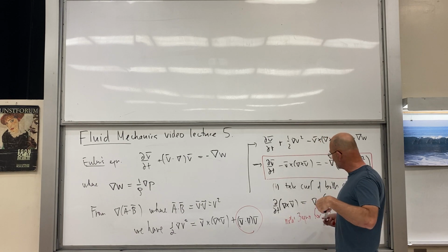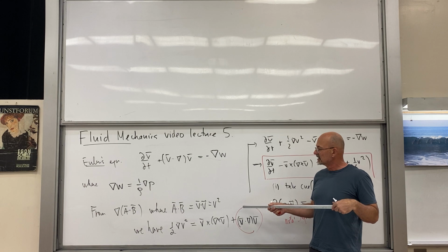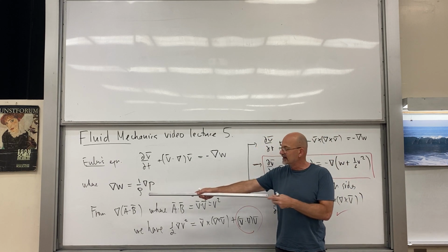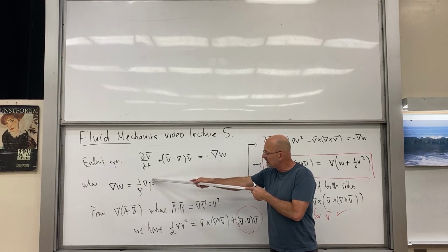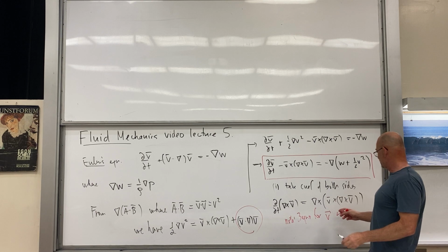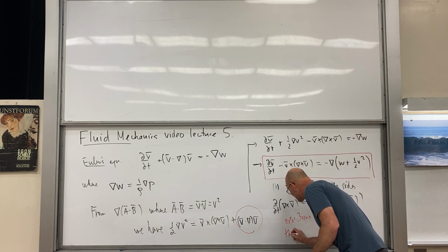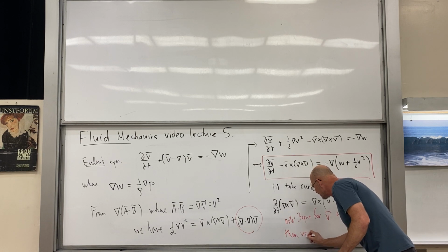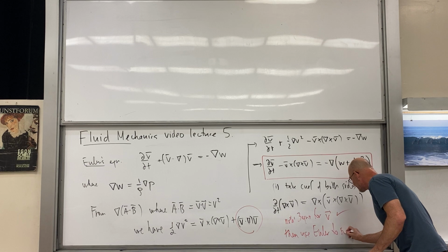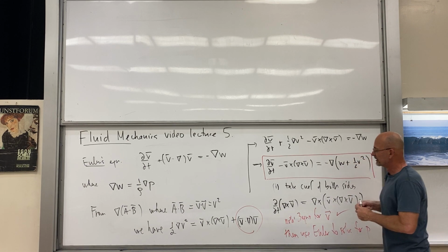Or you can go back into the original Euler's equation and solve for p. Because the density, which you'd also need, is actually just a function of position independent of that gradient of p if you go back into here. So I'll just put that as a note: 3 equations for v, then use Euler to solve for pressure P. Good.